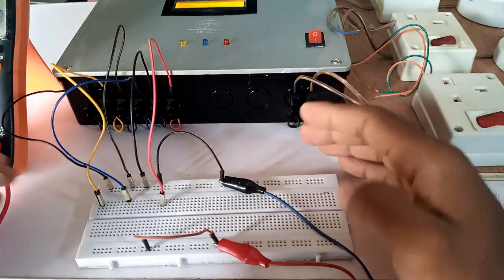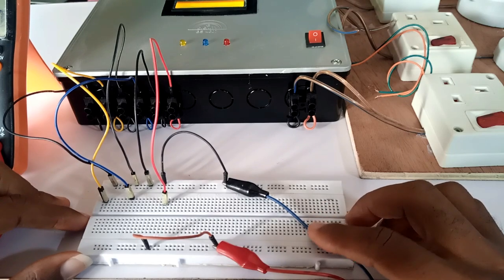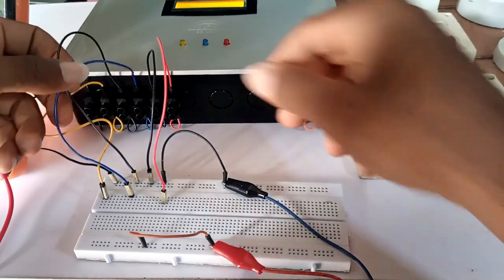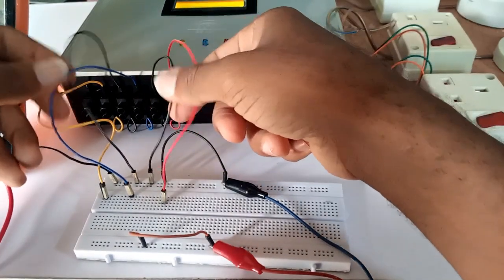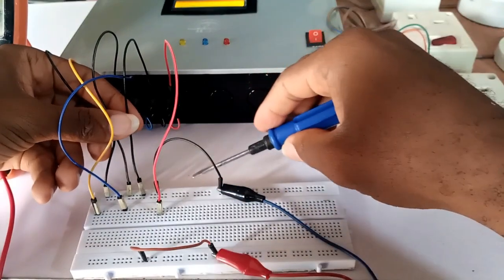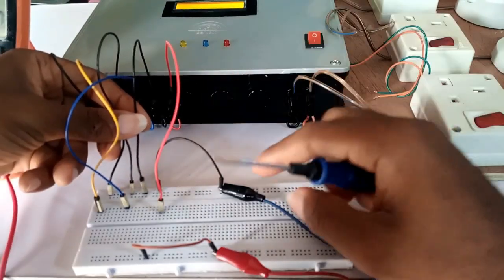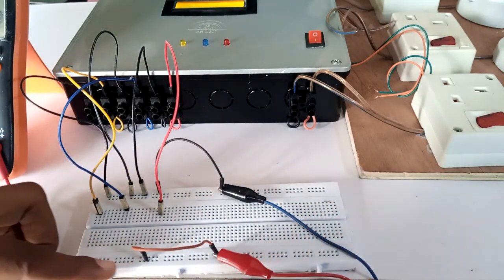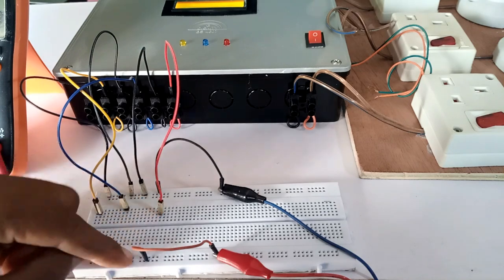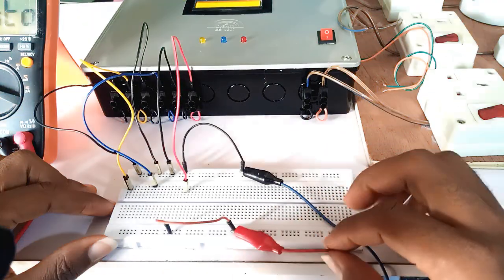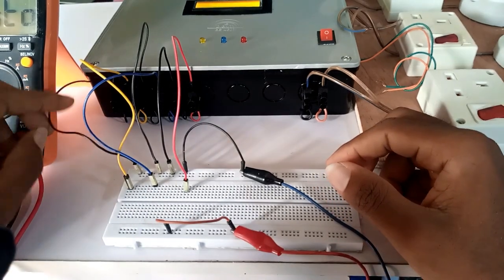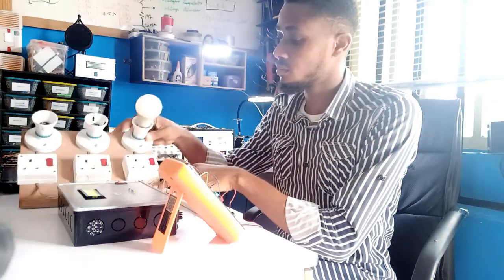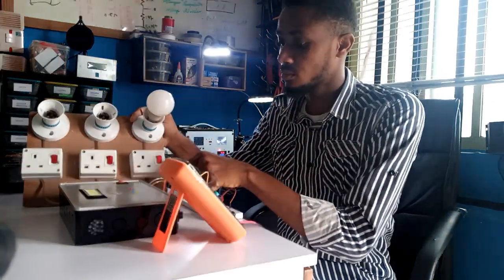For the first test which I'm going to conduct, I'm going to use jumper wires for each source. I have the yellow and black wire for the solar source, blue and black wire for the generator source, and red and black for the grid line. All the black neutral wires of all sources are connected together in the same rail on the breadboard, just as you can see, and I have them hooked up to the single AC line neutral source on the blue crocodile clip. The red crocodile clip wire is the single source AC live wire, which I'm going to momentarily connect each source live wire to, and finally I'm going to be using a white bulb as the load.